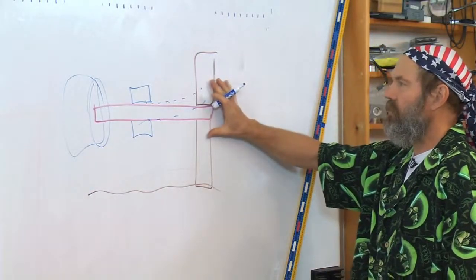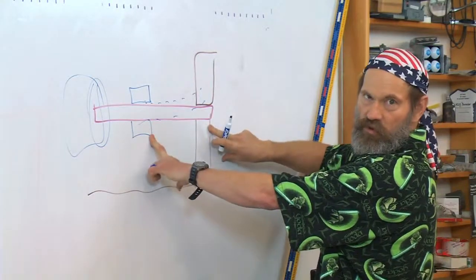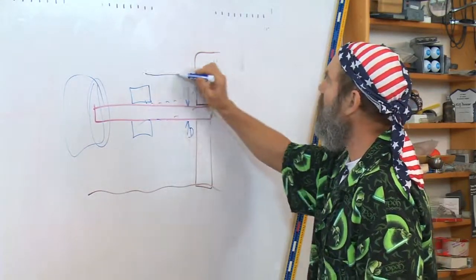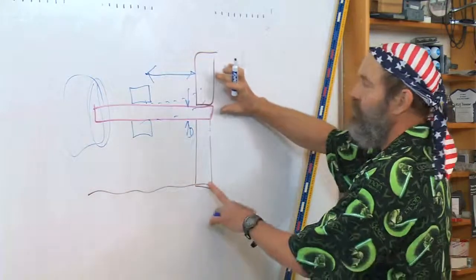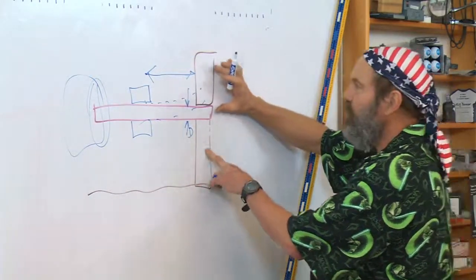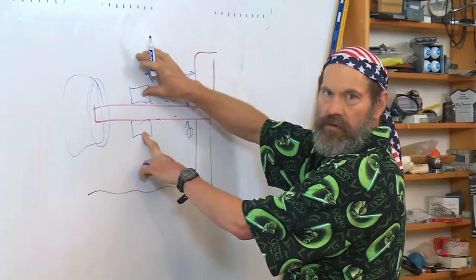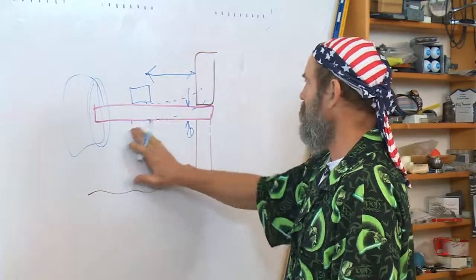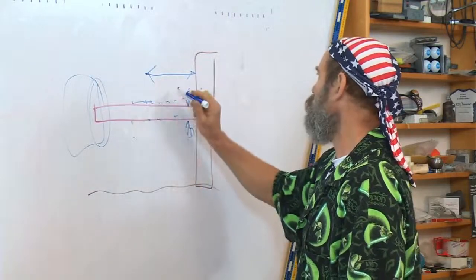The wheel, which is more than 3 characteristic dimensions away from the bearing, means the force from the wheel will now dominate the bearing and wreck the design. I'm going to move these bearings close to the wheel.